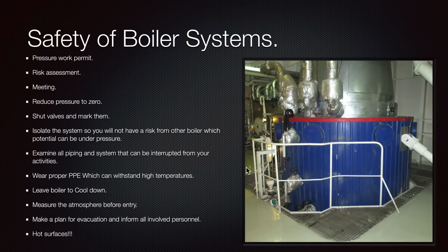The light that will be used must be of a closed type and have a specification that it is an intrinsically safe light, so it will not create any sparks in case there are gases present.